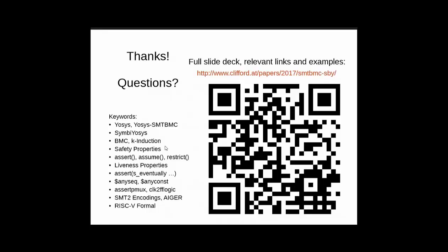I mean, the focus here, I hope it says it on the slide, but the focus here is verification of hardware designs. So when you have Verilog code or HDL code, there is one tool from the CProver people that can be downloaded for free. And I think the part they wrote is open source, but they incorporated a commercial parser that cannot be downloaded. However, I was not able to prove any non-trivial properties with that. I always got very, very weird error messages from the parser. I tried to reduce that to a minimal example, but all I managed to do was converting the error message into a segfault, and that was the point where I stopped.